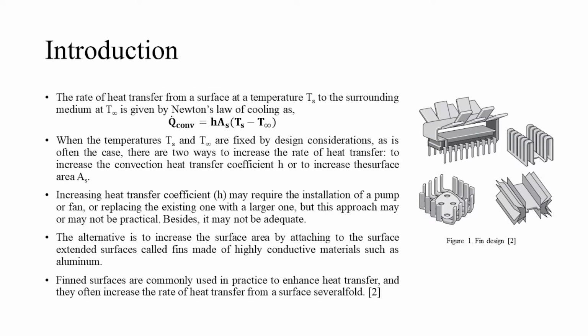The rate of heat transfer by convection from the surface maintained at temperature T_s and the surrounding temperature T infinity is given by Newton's law of cooling. Since the surface temperature and surrounding temperature remain constant, there are only two options to increase the heat transfer rate. First is to increase heat transfer coefficient h. Increasing h may require the installation of a pump or fan or replacing the existing one with a larger one. But this approach may or may not be practical. Besides, it may not be adequate.